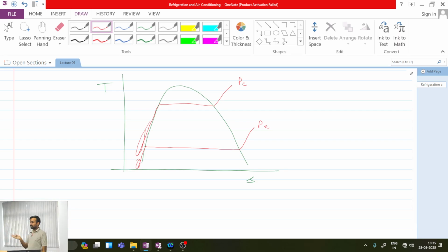Generally, the nature of the saturated liquid line is such that whatever constant pressure line on the TS diagram I have in the subcooled regime has a slope very close to that of the saturated line. Even when you learnt using steam tables in your thermodynamics course, it would have been taught that we can make one assumption: that this constant pressure line in the subcooled regime just follows the saturated liquid vapor dome. Are all clear with this point?